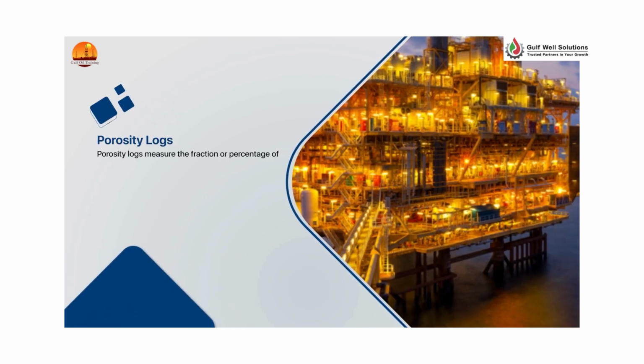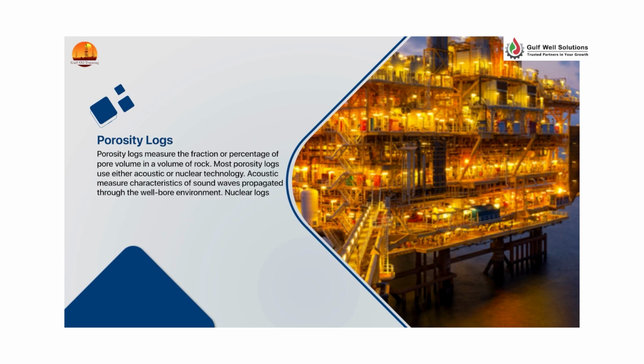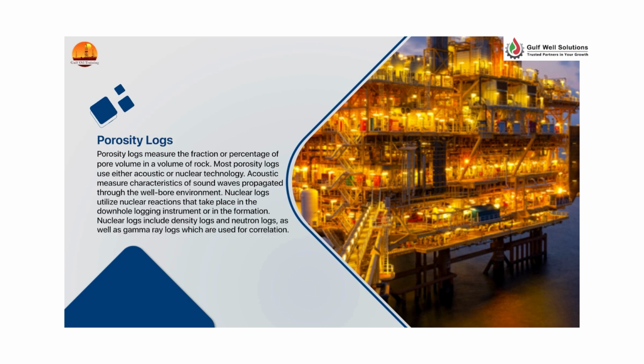Porosity logs. Porosity logs measure the fraction or percentage of pore volume in a volume of rock. Most porosity logs use either acoustic or nuclear technology. Acoustic logs measure characteristics of sound waves propagated through the wellbore environment. Nuclear logs utilize nuclear reactions that take place in the downhole logging instrument or in the formation. Nuclear logs include density logs and neutron logs, as well as gamma ray logs, which are used for correlation.